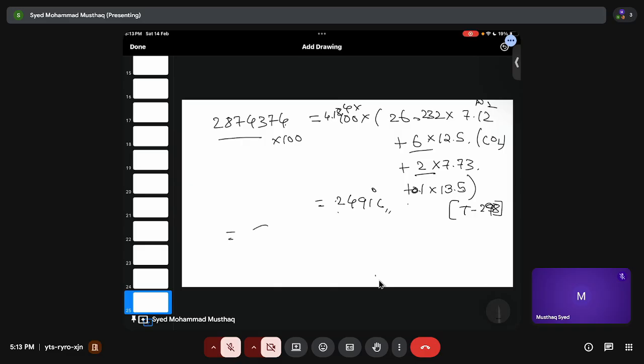You just add Ni Cpi, where Cp is the specific heat capacity at constant pressure. So you just add the number of moles of nitrogen times Cp of nitrogen, if this Cp is not a function of temperature. If it is a function of temperature, you cannot directly add this. Then number of moles of carbon dioxide times Cp of carbon dioxide, number of moles of H2O times Cp of H2O, number of moles of sulfur dioxide times Cp of sulfur dioxide.